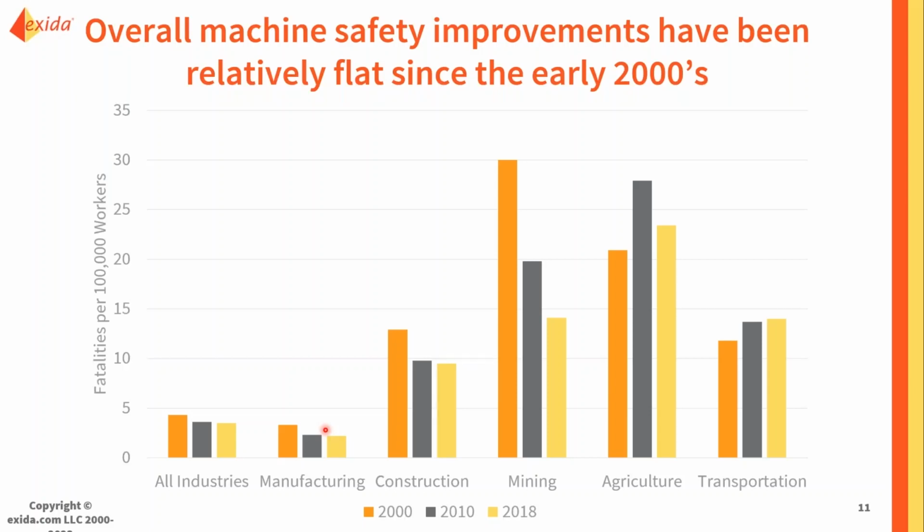And that is that having a machine safety program, actually managing it, making sure that the risk assessments are done robustly, making sure that everyone at the site or facility is familiar with them and understands where the hazards are, and not just covering it once, but having refresher training, making sure that you've got change management in place so that if changes happen, you can assess the risk for those, make sure that they're adequately reviewed and handled.